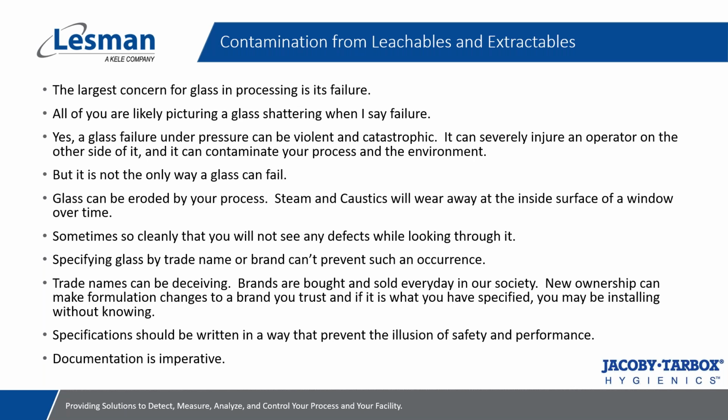If you're putting windows into your process and they are not a USP type 1 borosilicate, and then you are interacting with them through steam cycles and cleaning cycles, you are pulling the elemental properties of those windows. Most of them are made out of soda lime glass. Soda lime glass is the most common glass in the industry.